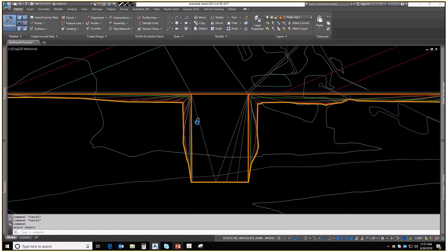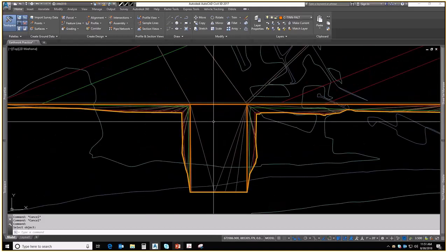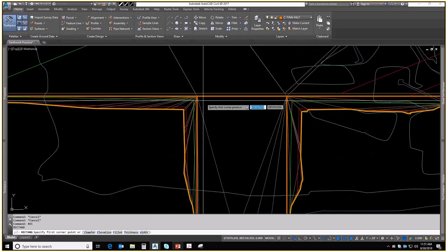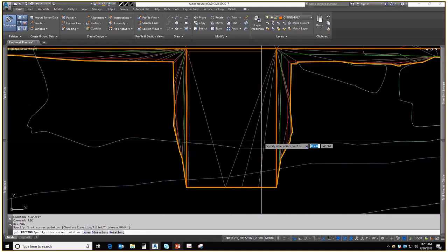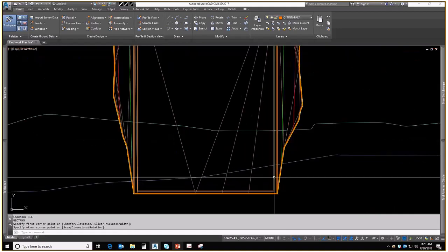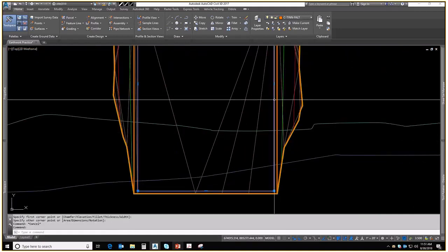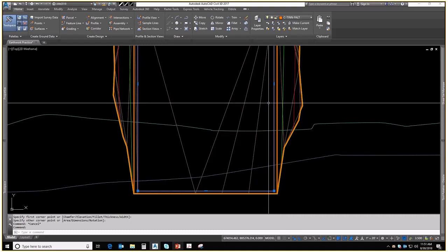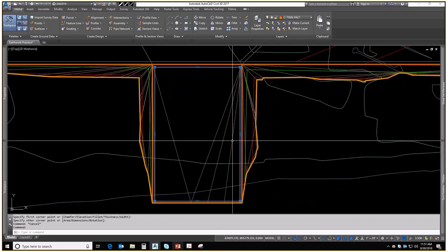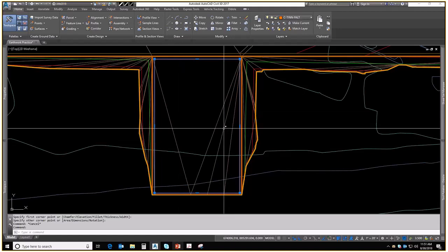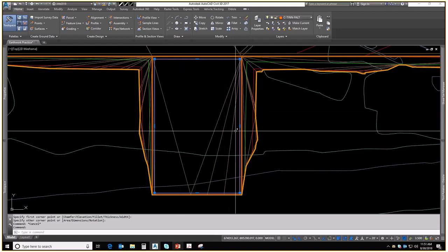Now say we have this connector taxiway that's bringing us into this apron. We could do the same thing, and once again, if you want this to be very accurate, I would suggest getting really close to these lines. You can't overlap boundaries very well before CAD starts getting really angry at you, so I would suggest maybe offsetting it a foot or 0.1 feet.